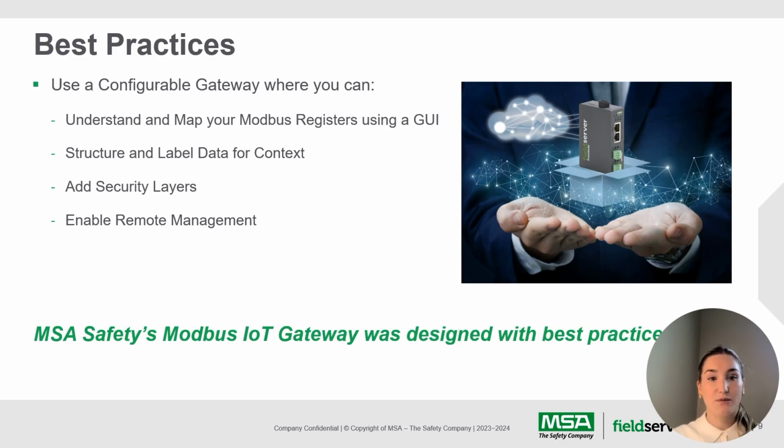And the last one would be enabling remote management. Once your gateways are deployed, especially in the field, you'll want to be able to monitor and manage them remotely. That includes updating configurations, pushing firmware updates, and diagnosing issues. Many gateways now support cloud-based fleet management, which is a huge lifesaver, especially for system integrators working across a dozen remote sites.